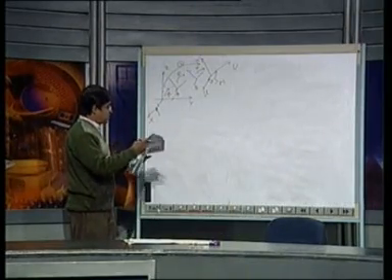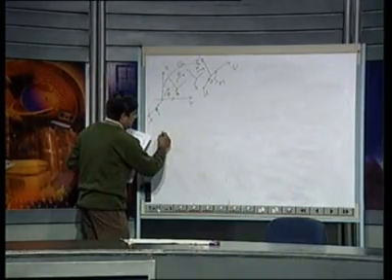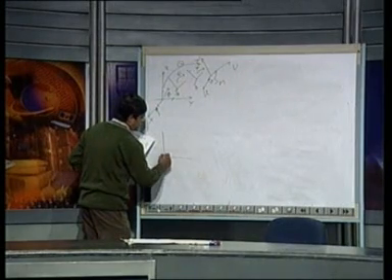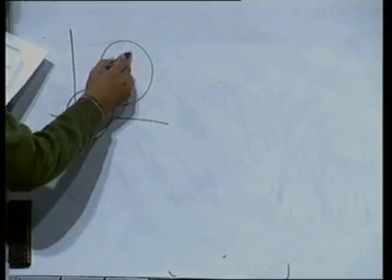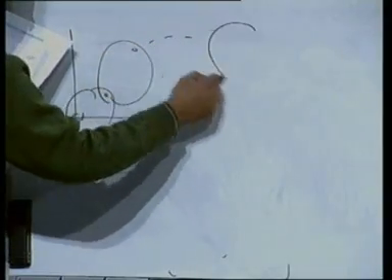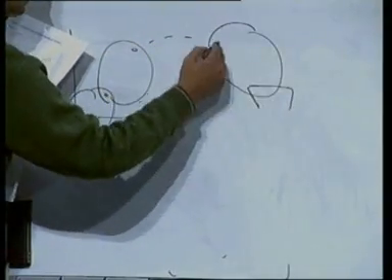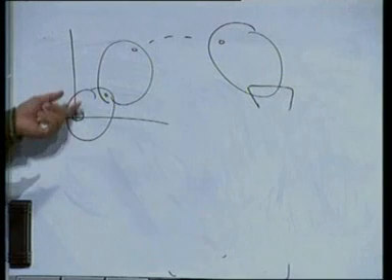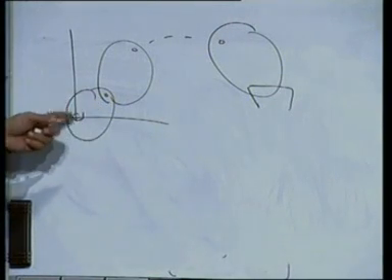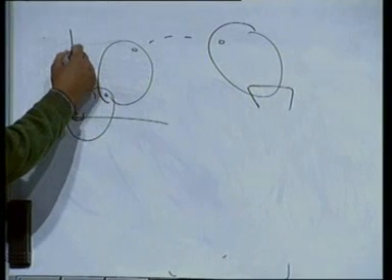Similarly, if we have a series of rotation and translation both, which means in a robotic system I have a series of rigid bodies, and on every body I fix a coordinate frame, one coordinate frame I can represent with its previous coordinate frame by a rotation and translation represented by this homogeneous transformation T 1.